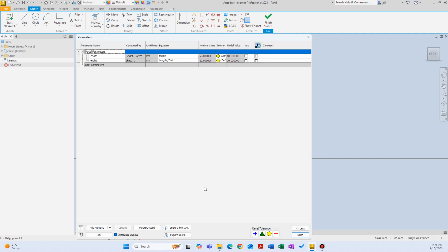Like I said, I think that project was about a ladder, but I designed phone cases, for example. I designed complicated sheet metal brackets and parts for some equipment. In this case, like I said, I had to design hundreds of different versions of it, and I didn't have to design it 100 times by manually changing the values. I just went into the parameters window and changed the values. I said, update this, and everything updated accordingly, because once I updated my reference value, everything is just in equations.